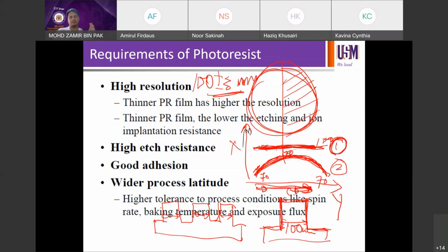Okay, and this CD drift can be in the form of many problems. For example, the whole wafer drifts, or just one section drifts, or just 50% drifts. Then this problem in its own way will lead you to different root causes. If it's just 50%, then it's a slanted issue. If the whole wafer drifts, then maybe dosage drift, or focus has a problem, or resist thickness is insufficient or excessive, or the resist suddenly expired, or the technician forgot to replace the new photoresist. So it could be due to thousands of different root causes. Okay, but the issue is CD drift.